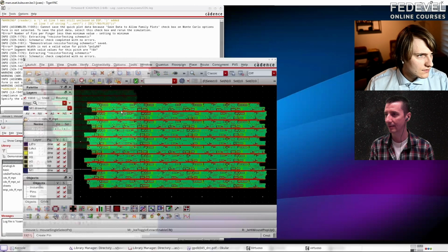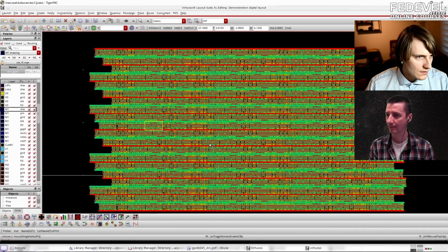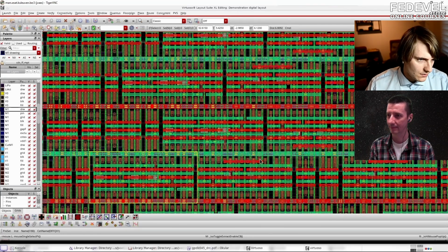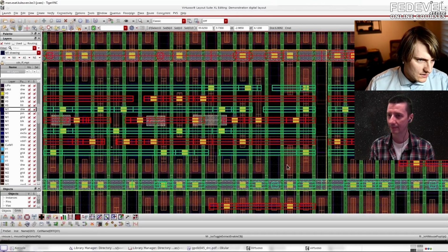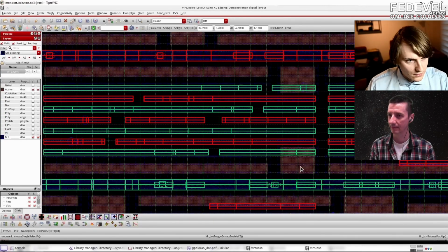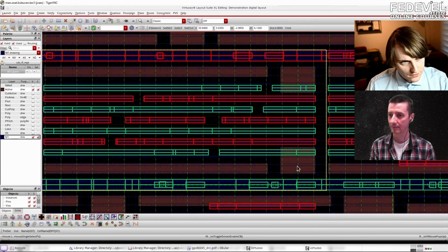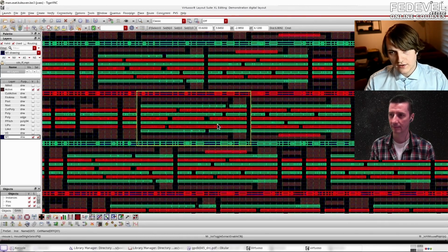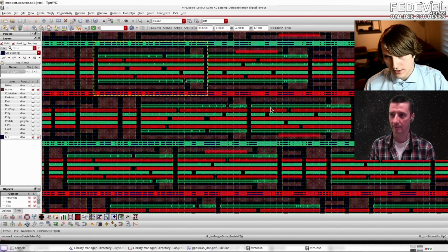Okay. Right. So you have the sea of gates here. If we zoom in and zoom in and zoom in, what we see here is on a very low level, each of these things, so the orange bit, is a transistor. So here, these are all transistors or parts of transistors, and then they're built into cells. And you can see this grid approach, and then a tool will translate your design into gates. It will place these gates and automatically connect everything.